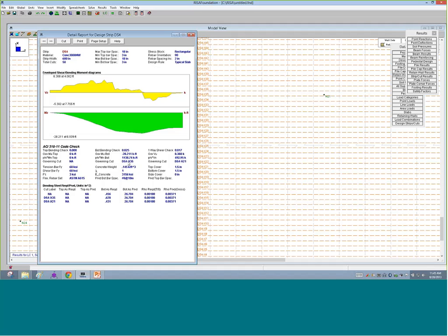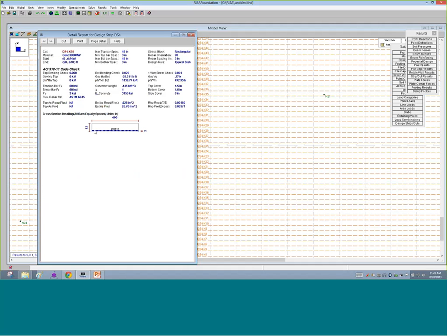To find out more about why that happens, you can see below here. You can click on this Design Cut 35, or you can just pop to the top and say Design Cuts. Click on that, and it will pop to the governing one, which is DS4-X35, and it tells us specifically what the forces were in that design cut, and why it was reinforced in that way.